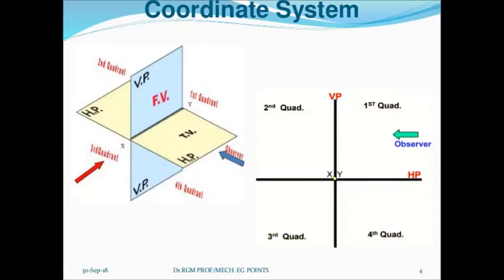See, this figure shows the coordinate system. There are 2 figures in this slide. One is an isometric figure, the other is an end view. Here, quadrants are marked from top right in anti-clockwise direction. See, the blue color shaded portion is called the vertical plane and the yellow color is called the horizontal plane. From that, we have to mark our first quadrant, that is top right.